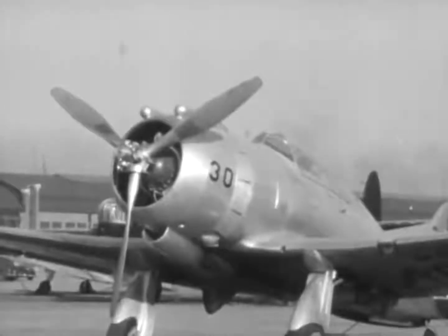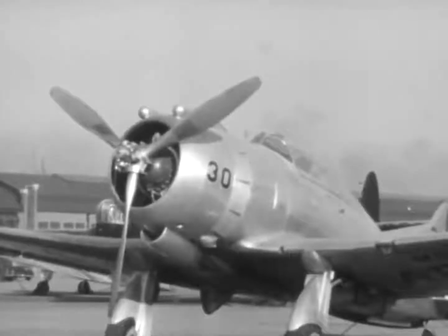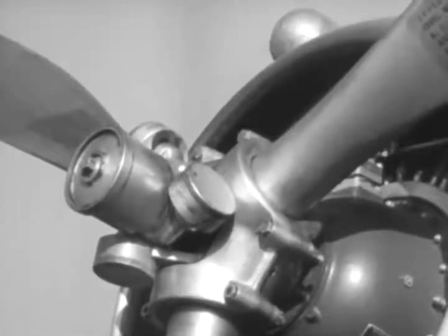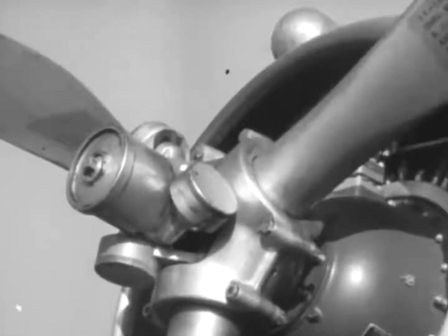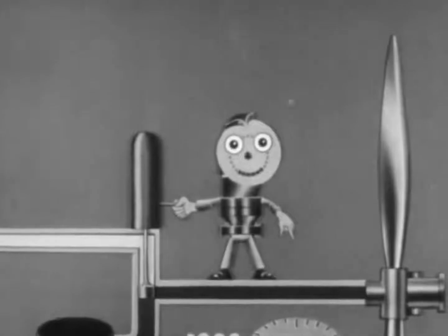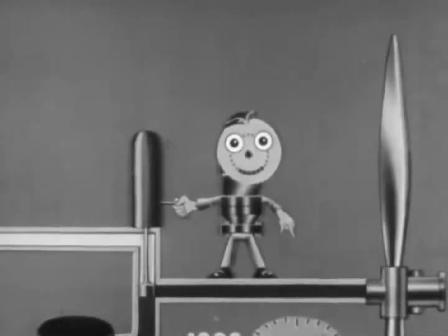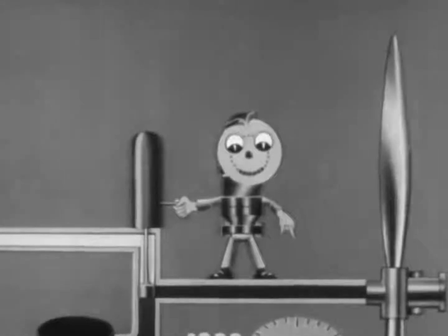Airplanes with still higher speed ranges need greater propeller pitch ranges. In addition, they require intermediate pitch positions between the two extremes. This need is filled by the Hamilton Standard constant speed propeller. A governor usually mounted on the nose of the crankcase maintains the engine speed at a constant RPM as set by the cockpit control. Should the engine speed drop, the governor notes the change.